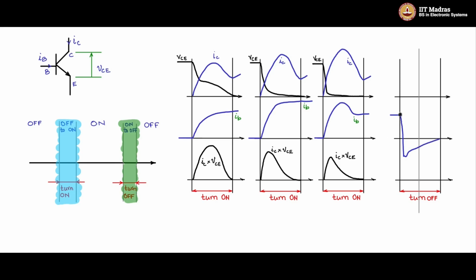So even though you have initiated removal of the base current here, you have stopped the base drive here, it takes some time for the base charge to recombine, and the area under this curve is the base charge that has been removed, and that takes a finite time.